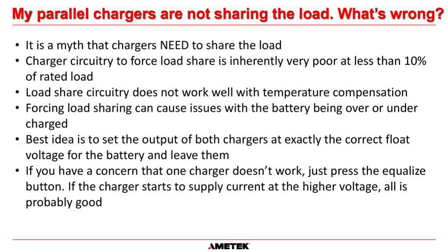Okay? And then if you have a concern that one charger doesn't work because it maybe has a slightly lower voltage than the other charger, then what you can do is just press the equalize button. And if the charger starts to supply current at the higher voltage, all is good. And then you just put it back to float.